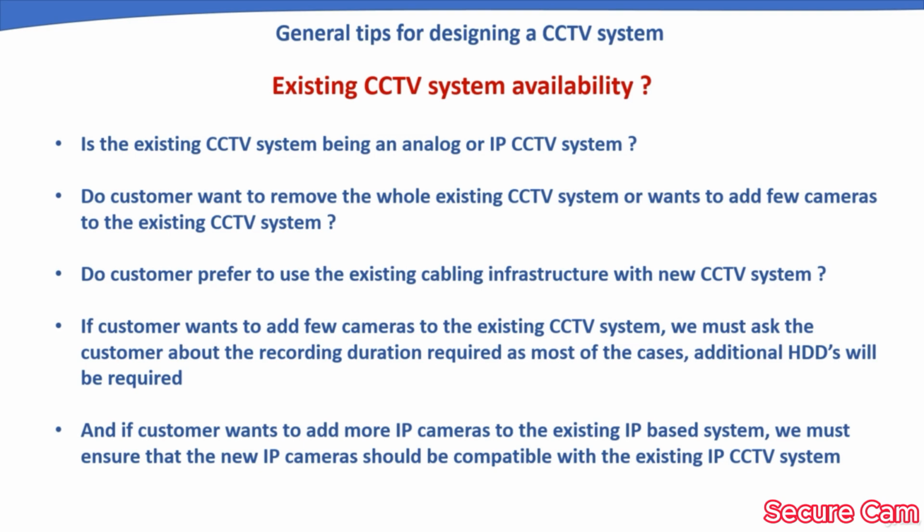Many times the customer wants to use their existing cabling infrastructure, but as a CCTV system designer, we must ensure that the existing cabling infrastructure meets our new CCTV system requirements and the existing cabling is in good condition. Next point, if the customer wants to add a few cameras to the existing CCTV system, we must ask the customer about the recording duration required, as in most cases additional hard disk drives will be required.